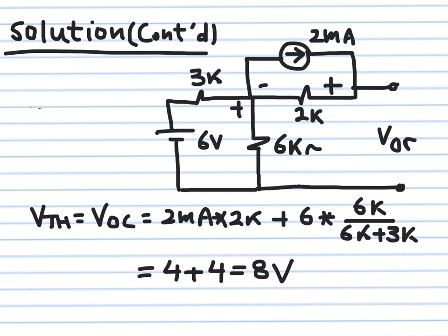So this is what I did, I created an open circuit, and now I want to calculate this voltage. This circuit is very special because you can see these are actually two separate circuits, and they only meet at one point. So there is no return of the current of this 2 milliampere to this circuit here. So this 2 milliampere will only flow here, and this loop will be on its own as well. Okay, so these are actually two independent circuits.